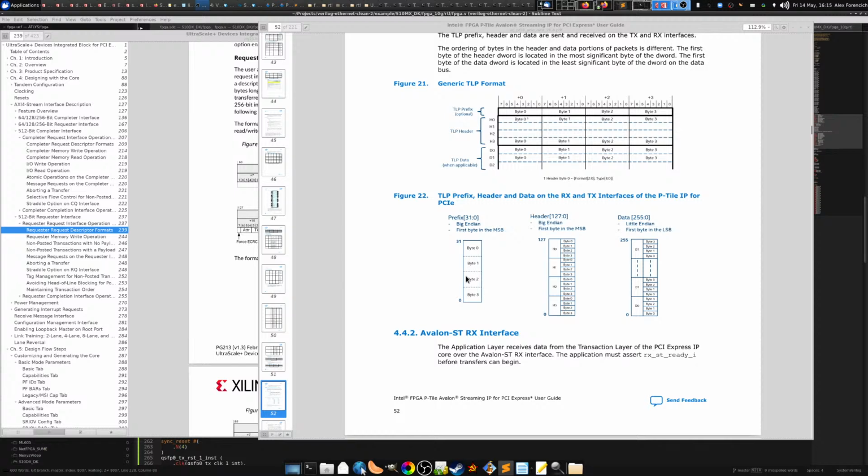So what I'm working on in the PCI Express side of things is basically converting the DMA engine and some of the other PCI Express components to speak something very similar to this P-Tile interface. And then on all of the other components, including the Xilinx UltraScale, as well as P-Tile and the Stratix 10 MX, which has the H-Tile, I'm just going to basically have to write adaptation logic to convert whatever that particular FPGA wants, whatever the hard IP core wants, to this kind of format.